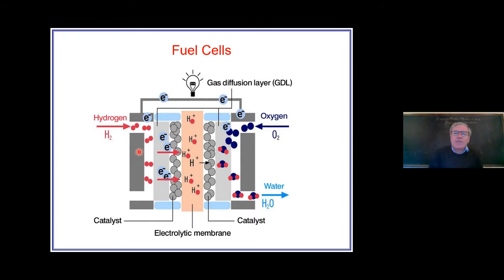And again, what happens is that the gases move through a fibrous porous material called the gas diffusion layer. And you want the gases to be able to move in, but the water that you produce, you want it to escape. So here you're having a problem where you don't want to trap the fluids in the pore space, you want them to flow. And of course, that's exactly the same as what you might traditionally want for oil recovery, right? If you want to recover a lot of oil, you want the oil to move over a wide saturation range. And what you normally do is you get the oil out by injecting water, by pushing in water to displace the oil. So you want both the oil and water to be flowing over a wide saturation range.